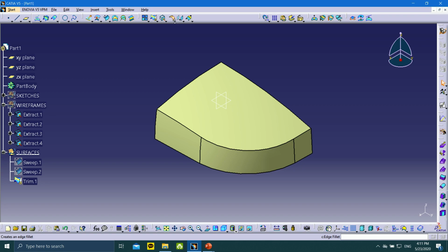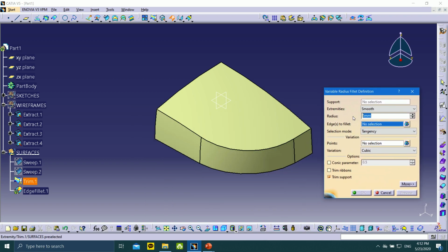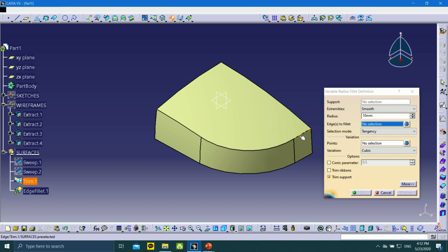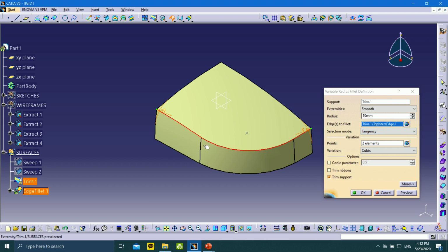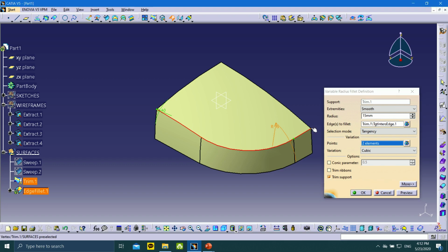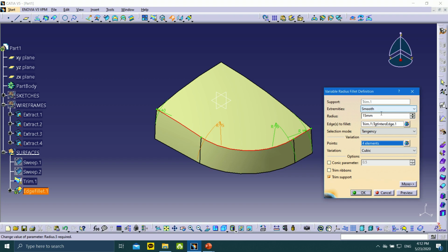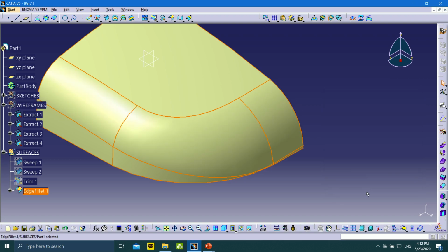Okay, I think it's so easy for you. Go in here and select this icon variable fillet, which is the 10 radius for this and this. This one 10 radius, and element for in here is select 15, and also in here select 15, 15, 15, and in this part you select 10. So this one very easy. This one 10, 10, 15, and 15.